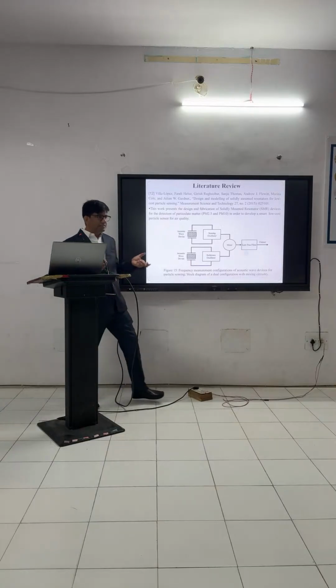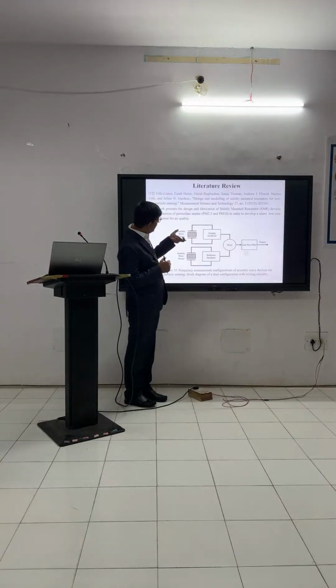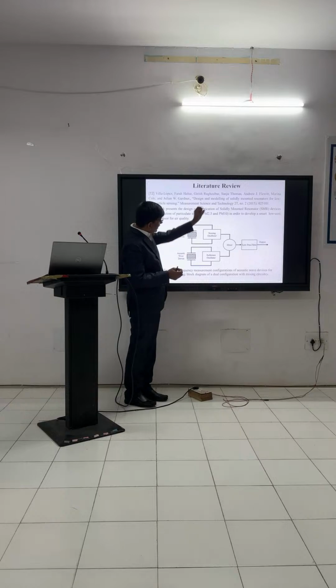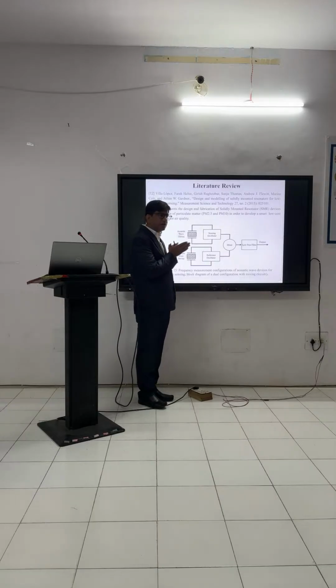For that, we can design an interfacing circuit for the device. What do you have in this interfacing circuit? You have one FBAR and another FBAR with a sensing layer. For example, we want to design it for a particular sensing purpose. So we have one device without a sensing layer and another device with a sensing layer. Clear? Then we have this sensing oscillator and reference oscillator, and then we have a mixer. What will this mixer give? The mixer will give the difference of both resonators' frequencies.